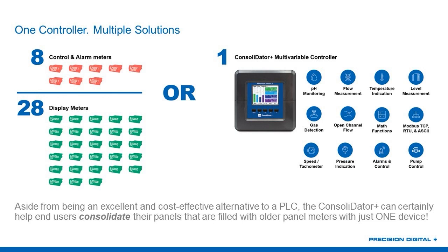Someone asked, does it overheat when all 24-volt loop supplies are operational? That's a really great question, and the answer is, well, it depends. So you caught me on a technicality there, Ash. Even though each and every single 4 to 20 input has a 24-volt supply, you can have up to 28. There is a slight caveat. We cannot exceed 1.6 amps, or 1,600 milliamps. So the answer to your question, Ash, is no, because we won't allow it to, but I see where you're getting at.